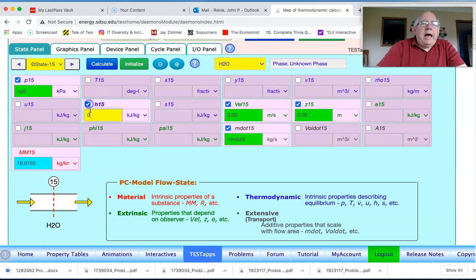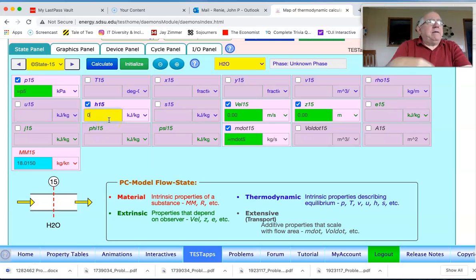But now what we have to do is we have to add the value of the enthalpy at that point, which is the value of what came in, H3, minus then the isentropic work, which is H3 minus H5, times 0.85. And so this enthalpy, oops, I forgot that was a times.